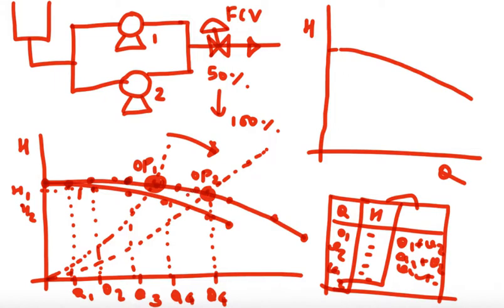So at that time you will have a higher gain in flow rate, but slightly higher loss in head also. But you don't have to worry about the head when you are in parallel operation. You are more worried about the flow, not the head, because you are achieving the head with the single pump also.